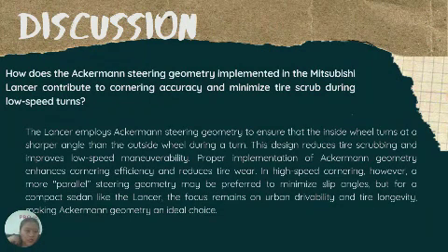The next discussion is how does the Ackermann steering geometry implemented in the Mitsubishi Lancer contribute to cornering accuracy and minimize tire scrub during low speed turns? The Lancer employs Ackermann steering geometry to ensure that the inside wheel turns at a sharper angle than the outside wheel during a turn.